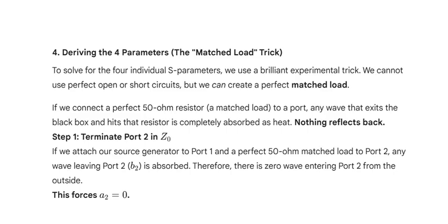Deriving the four parameters, the matched load trick. To solve for the four individual S parameters, we use a brilliant experimental trick. We cannot use perfect open or short circuits, but we can create a perfect matched load. If we connect a perfect 50 ohm resistor, a matched load, to a port, any wave that exits the black box and hits that resistor is completely absorbed as heat. Nothing reflects back.